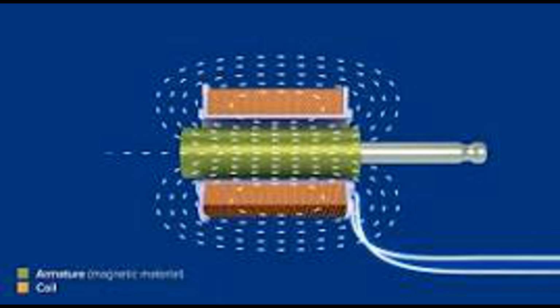security systems, electromagnetic brakes. 4. Proportional solenoids. Description: these solenoids provide variable force or displacement in proportion to the input current. Operation: the force exerted by the solenoid is proportional to the amount of current flowing through the coil. This allows for fine control of the position and force of the core.